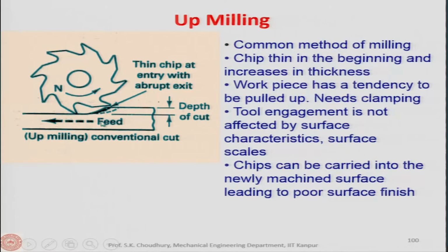Here is the popular categorization of milling. This is called up milling, so you must be familiar with that. This is the milling cutter and this is the workpiece. Up milling is when the direction of rotation of the milling cutter and the feed movement given to the workpiece are opposite. This is a common method of milling actually. Mostly you will see up milling used in practice.